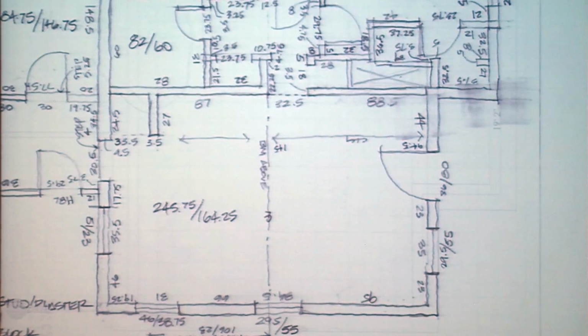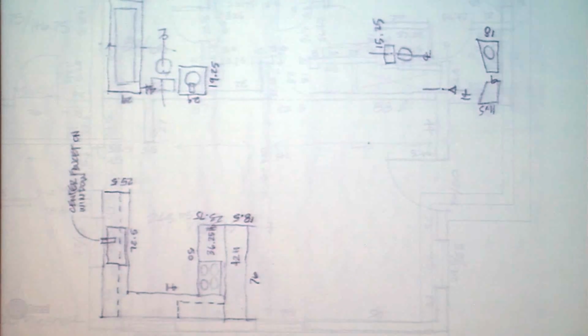Then, this is a good trick too. I always bring trace paper with me. You notice that there are not any kitchen fixtures or bathroom fixtures on this drawing. I want this drawing real nice and clean. But what I do is lay my trace paper over and go back and measure all my fixtures. This way, it's like a layering system in the field. So now I can record all the bathroom fixtures, make any notes I need to make, and be really sloppy about it. Maybe there's some special condition I want to really get in detail, but you have the ability to do so.